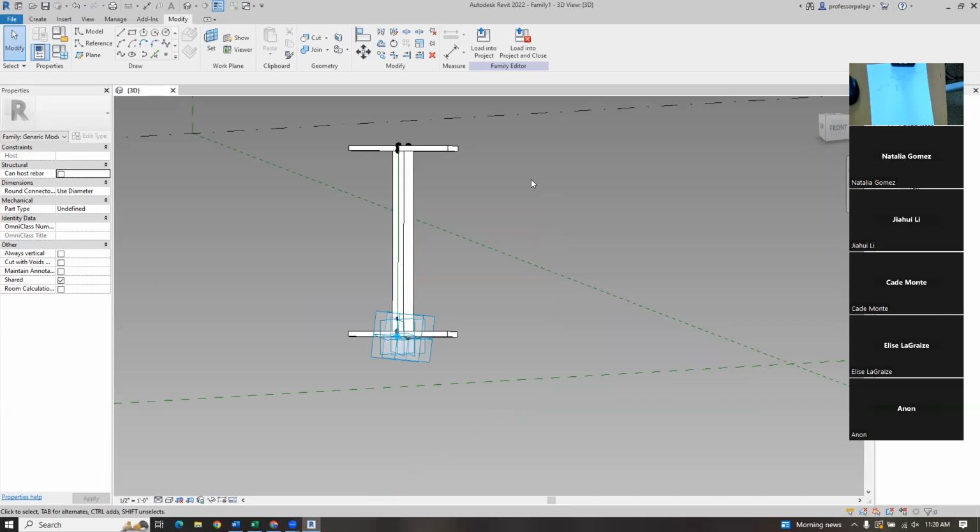Why would we want the top chord, bottom chord thicker than the webbing? So these are bending, right? So why would we want the top and bottom thicker than the intermediate member between? So in bending, when anything's in bending, remember, let's say there's a neutral axis and then there's the blank and blank at the top and bottom. What are those things at the blank and blank?